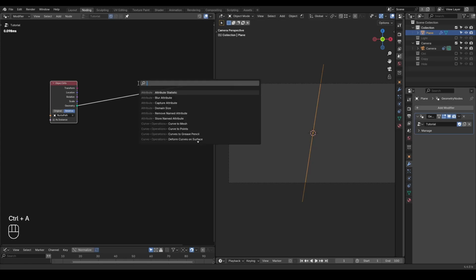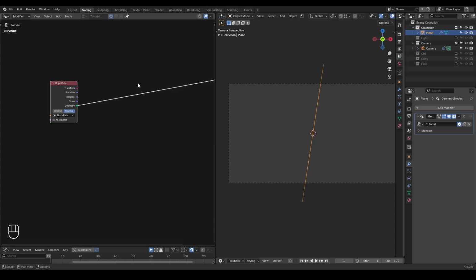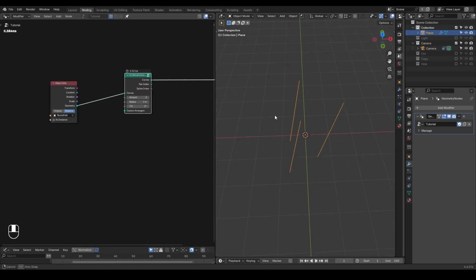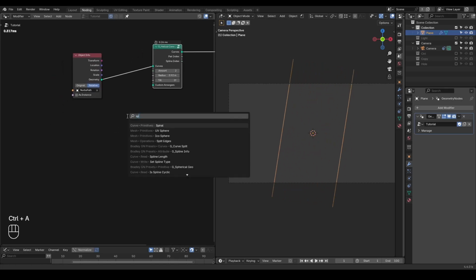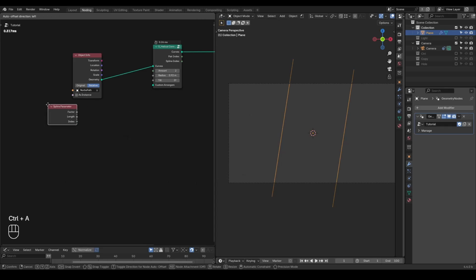And in the deepening transition effect, we're using these helical connections, which is essentially just splitting one curve into multiple parts. And in this case, I'm just using 2. So we are using a single radius to control this splitting distance. And this is very important, where you can put a spline parameter to control this radius.